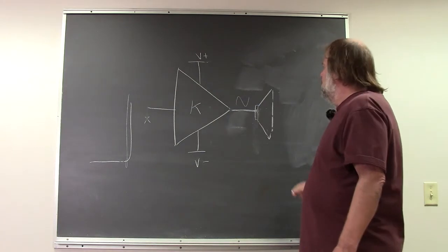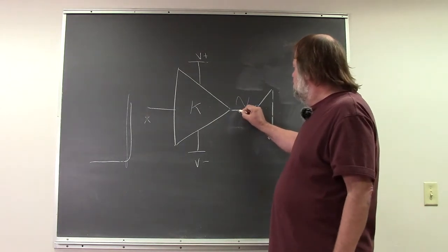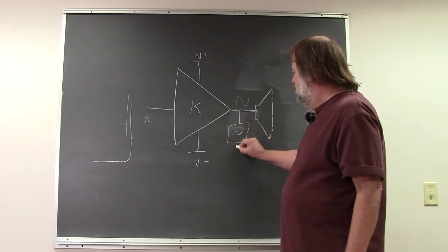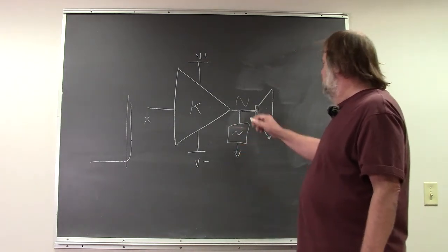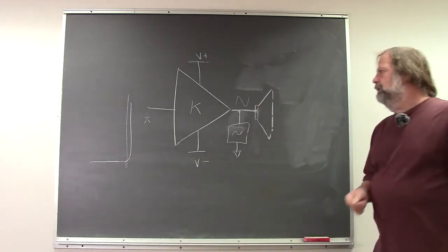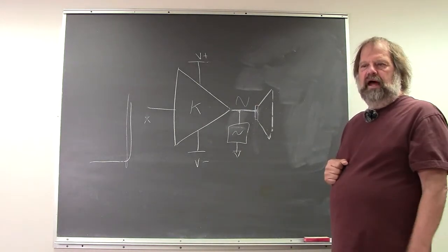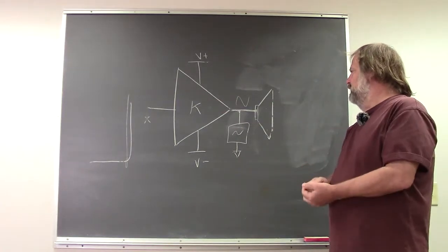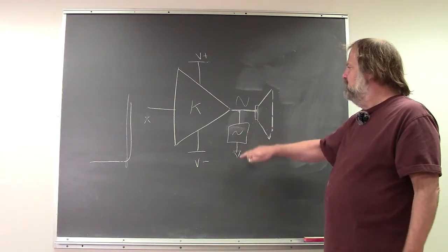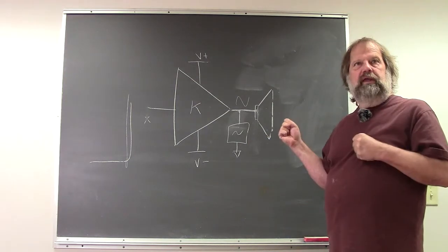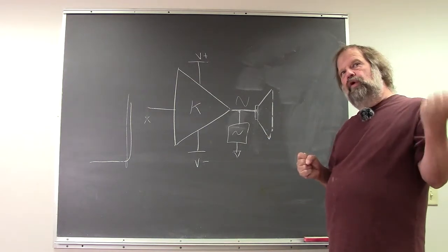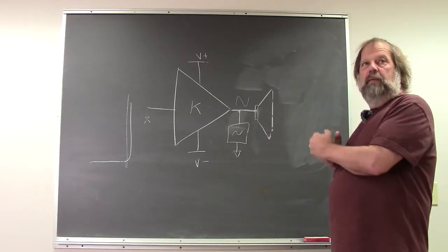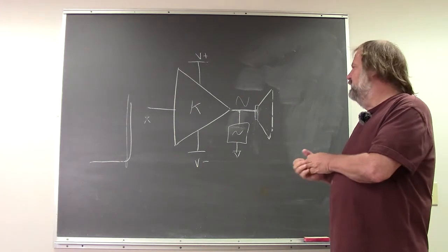And that is, I could simply measure, say with an oscilloscope, that's my oscilloscope, not a very good one, across the loudspeaker, and I could start playing it loud, say with a music source or a sinusoidal source, and I could just watch for clipping, or measure how many volts it swings for a given sound pressure level, and I could then extrapolate up if I wanted to, so I don't have to go all the way to full scale.